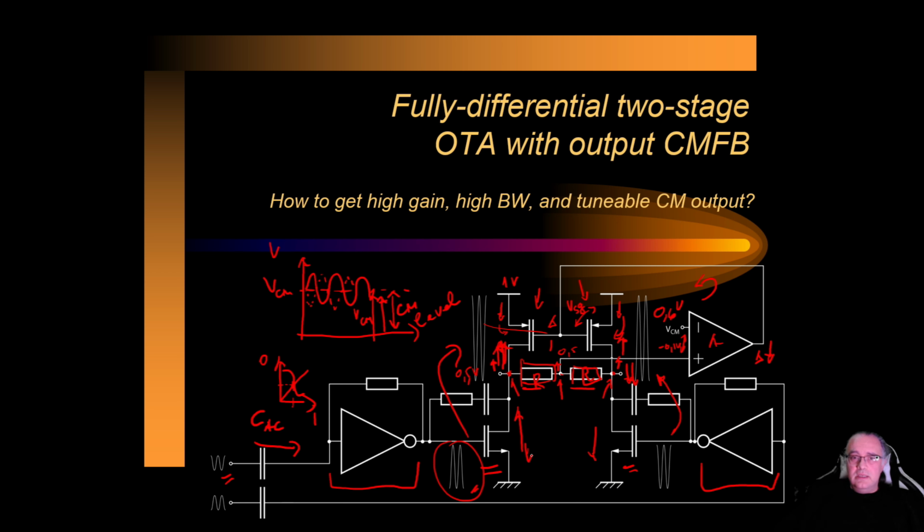So basically you can also imagine that the on resistance of these current sources reduces, and hence if you imagine the pmos transistor and the nmos transistor as sort of a resistive divider of the voltage, then the voltage in the middle will go upwards. As the voltage goes upwards, of course, this node here in the middle will approach 0.6, and as it approaches 0.6, then this will settle to a certain value and will no longer need to change,